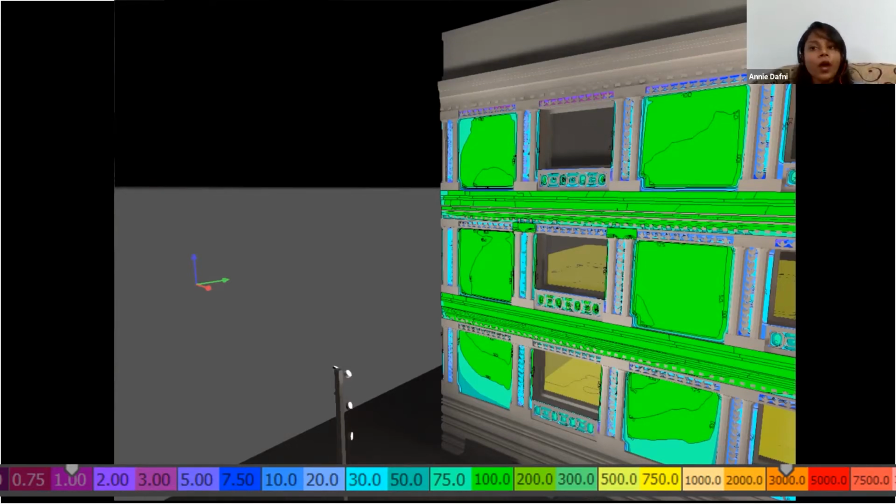Whereas if you have a very isolated building or a high rise building where there is not much lighting from street lights or other buildings contributing, then even a very low lux level of 20 or 30 would make your building stand out. So we need to make sure where your building is set and what the ambient lighting condition is.